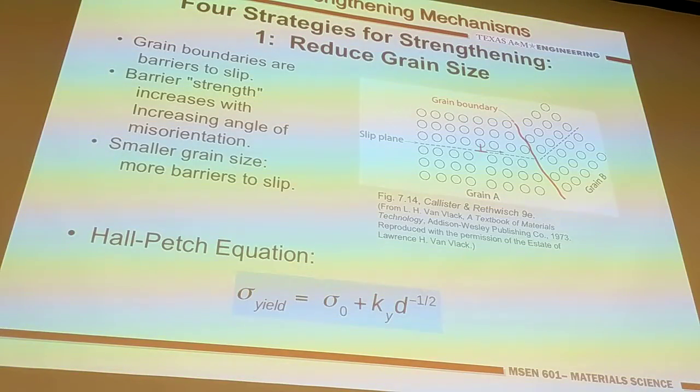So what you need to really deal with is the yield strength. For example, if I want to enhance the yield strength, all the business you want to do for conventional metals is to slow down dislocation motion or stop dislocation motion if possible. This makes sense, right?